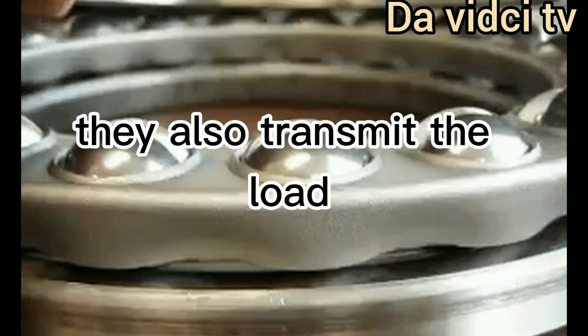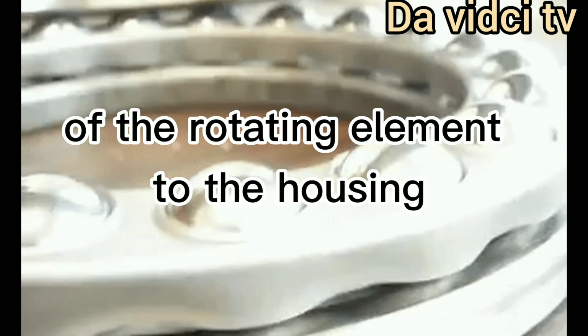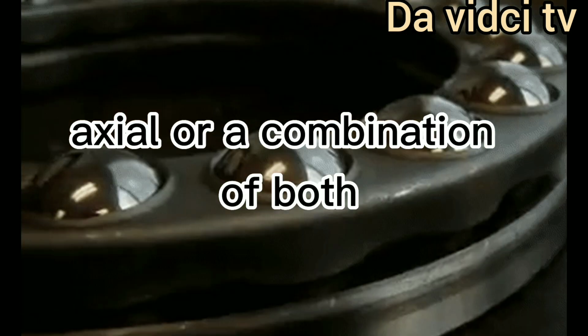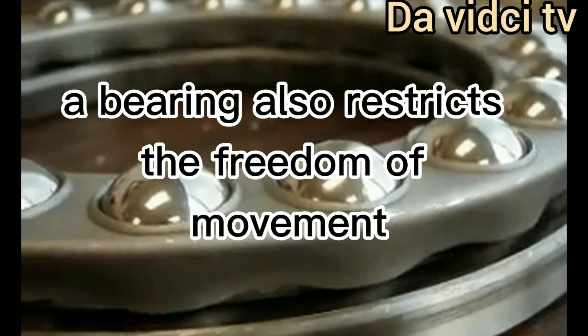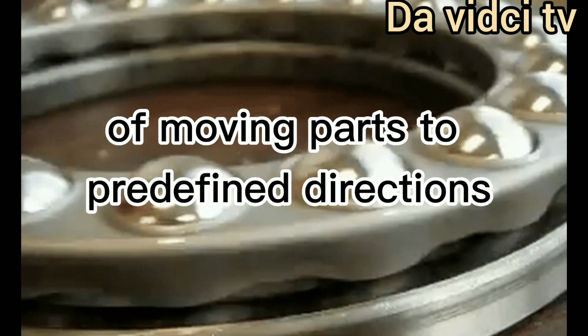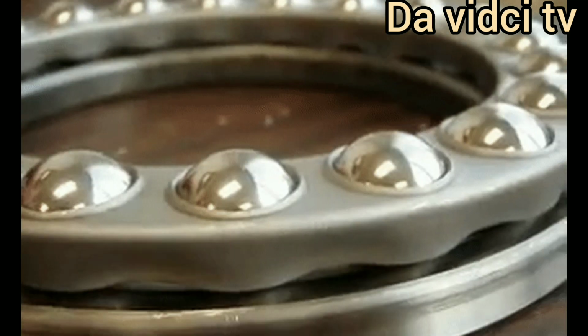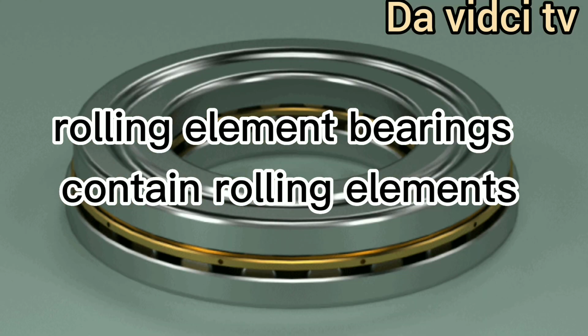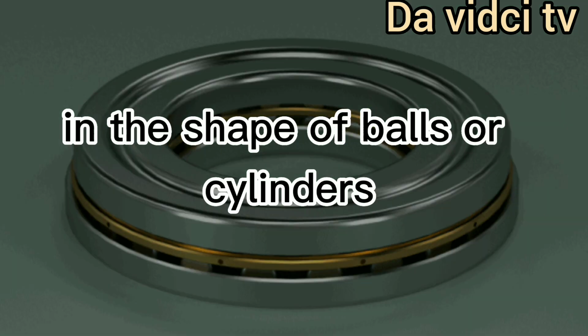They also transmit the load of the rotating element to the housing. This load may be radial, axial, or a combination of both. A bearing also restricts the freedom of movement of moving parts to predefined directions as discussed above. Rolling element bearings. Rolling element bearings contain rolling elements in the shape of balls or cylinders.